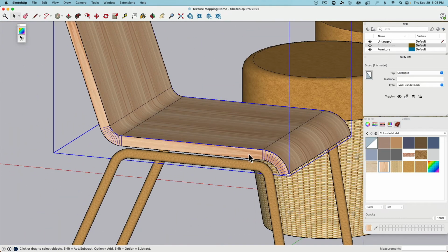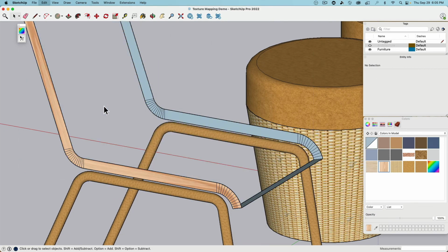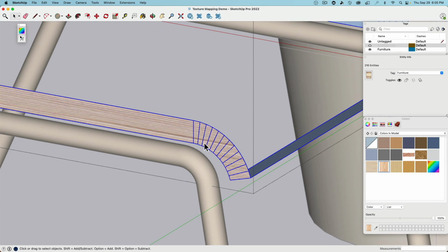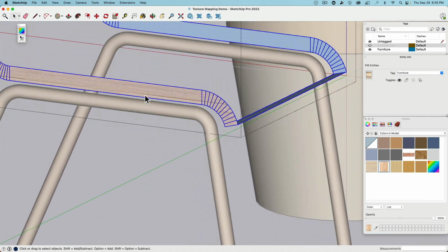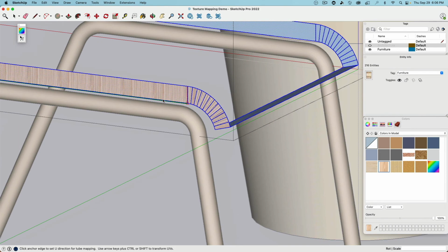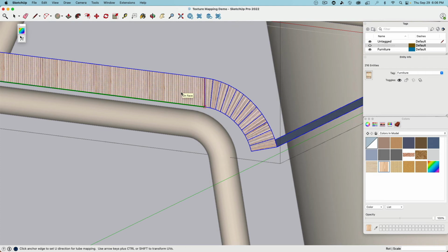And now here, this part, so the sides, I'm hiding these, so you see I'm working just on the sides. They need to get a different material. Okay. There we still now have this kind of issue, not a big deal. Again, click, click, click, right click, tube. There it is. Now this is actually rotated incorrectly, the material. We can type in 90 degrees, lower right corner, for example, press enter, and then it should rotate it.